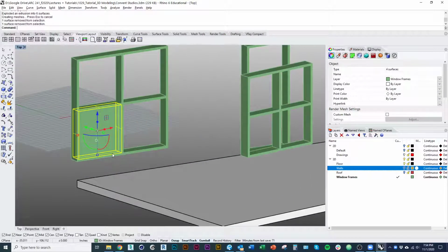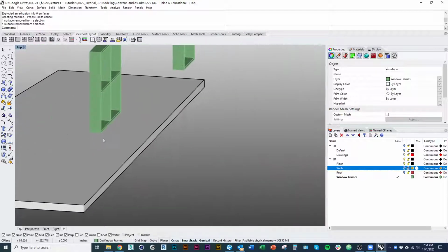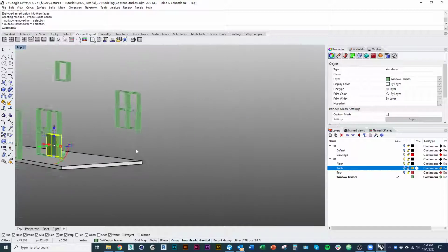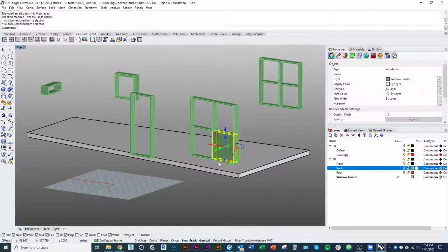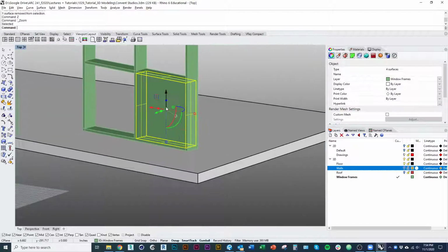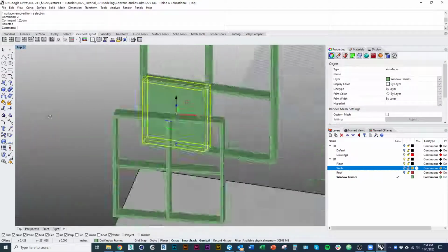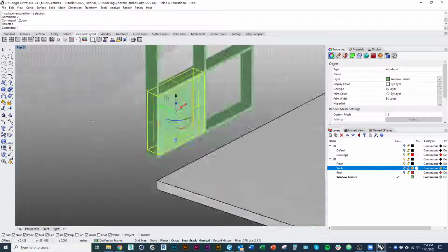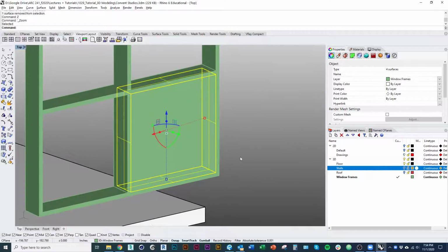By the way, if you have trouble like that, where when you orbit, things fly out of your view, what you can do is just quickly go zoom or Z, enter, and hit the option selected or hit S, enter, and it'll make that object the center of your orbit. So you'll see me do that a bunch. I actually have a hotkey for it. And that'll just make it easier to navigate as you're going along.